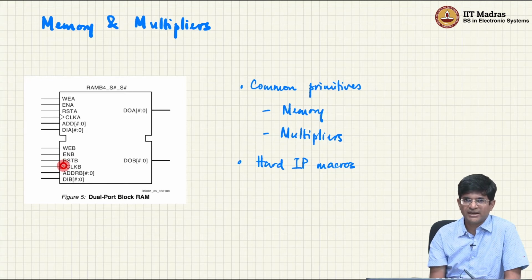Instead of that, by directly having a memory block like this, it becomes much more efficient, much more compact. Another instance like this is the so-called multiplier IPs, right? There are DSP slices in modern FPGAs which are very good at performing multiplications of numbers. In recent FPGAs, you can have up to one 25-bit number multiplied by another 18-bit number, and all being done at an extremely high speed, right? Because these are hand-tuned to have really good performance. So modern FPGAs have evolved more and more along those lines, right?